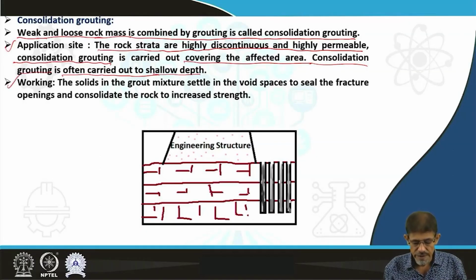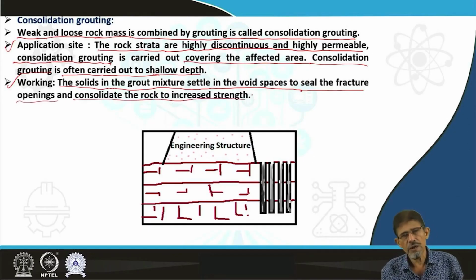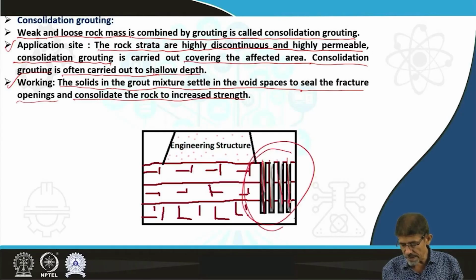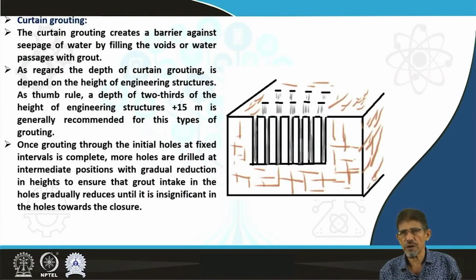As far as the working of consolidation grouting is concerned, the solids in the grout mixture settle in wide spaces to seal the fracture openings and consolidate the rock strata to enhance the strength. You can see a number of holes consolidated near a particular targeted zone, and this type of grouting we recognize as consolidation grouting.